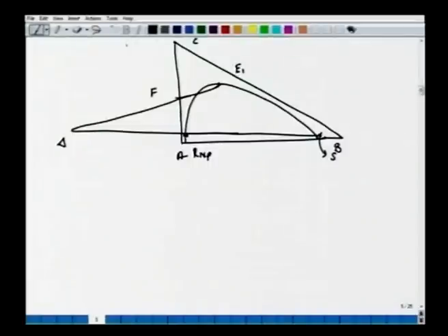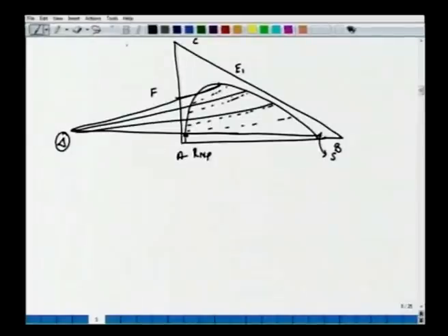Now there is a possibility, and there are several such tie lines. So these are the equilibrium curves. Let's say the slope of the equilibrium curve is like this. All right. So the way we did in case of distillation, let us find out what is that del min, which corresponds to the operating line, which we have drawn in several previous cases like this, becomes or coincides with this tie line.